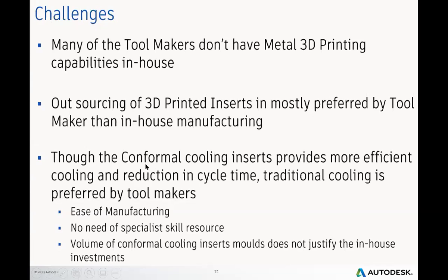And though the conformal cooling insert provides more efficient cooling and reduction in cycle time, traditional cooling is preferred by tool makers. That is because of ease of manufacturing, no need of specialist skill resource, and the volume of the conformal cooling insert mold does not justify in-house investment. So the challenge is this.